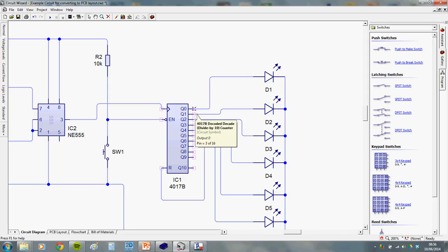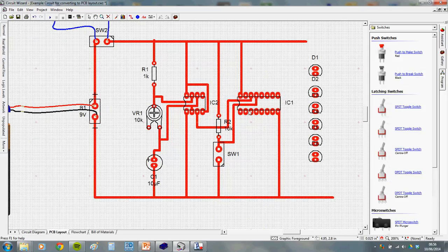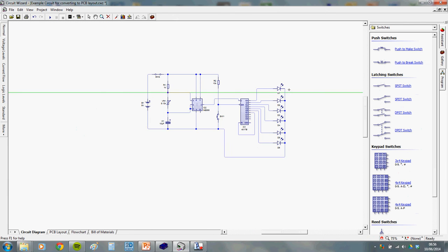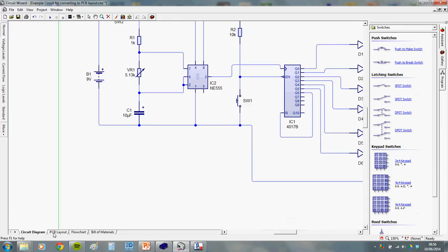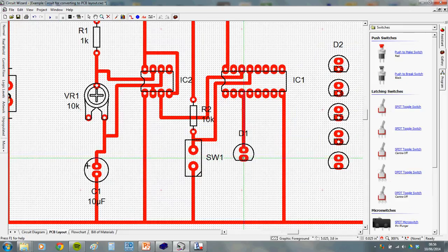So I'll just do this one, then I'll pause it and come back again. So this first LED is actually connected to pin number 3 on the diagram. How do we find pin 3? Well, there's the notch, there's pin 1, 2, 3. So our first LED is actually hooked up to that. And the other end of it went to 0 volts, so we'll put that on. Okay, I'll pause it, and I promise I'll be back this time when it's finished.